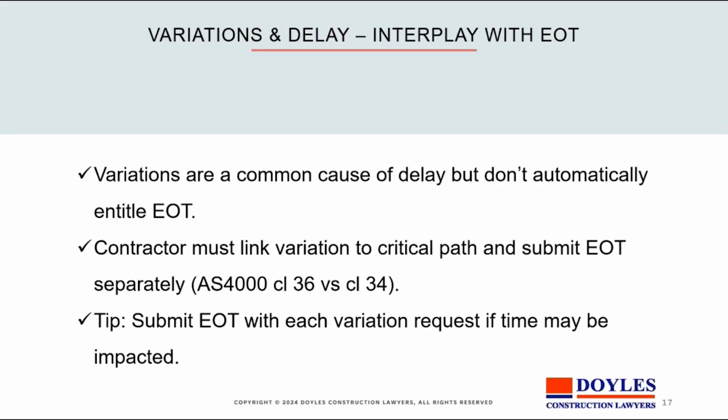So it's important when you look at variations, they have quite an element of specification and design to them in many cases, and that causes delay because all of those things can't be organised in an instant. The issue, however, for a contractor is to be very careful to respond back to any unclear variation with a request that it be properly defined as soon as possible, and noting the delay might be a result of it.